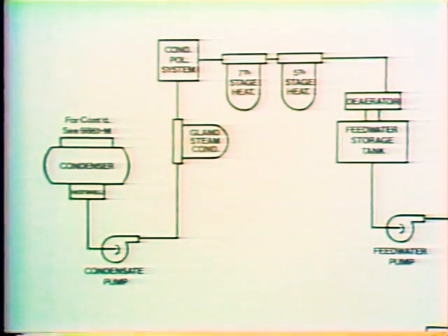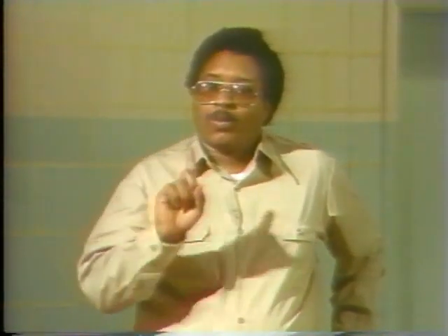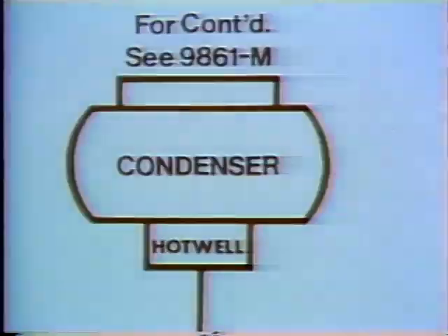Now that you know how P&IDs are identified, let's focus on this one. We'll begin by identifying all of the major components in the condensate system, and then go back and add the instrumentation necessary to make the system work. You'll soon see how complicated P&IDs can become, but if you treat them like we did the legend and approach them one section at a time, they're much easier to understand.